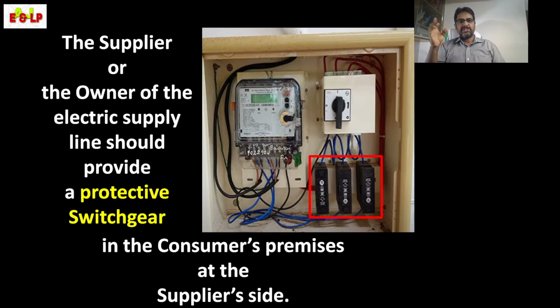We also covered what making capacity and breaking capacity are. A switch has only making capacity, not breaking capacity, and a circuit breaker has both current ratings, making capacity and breaking capacity. Making capacity is rated in amperes and breaking capacity in kiloamperes, but a switch fuse has breaking capacity. Anyway, I am stopping this part.